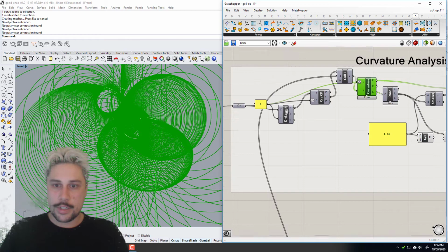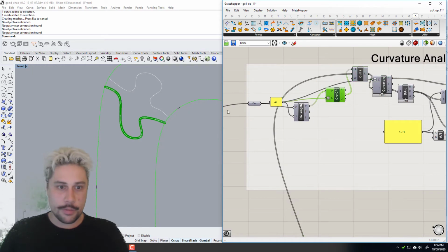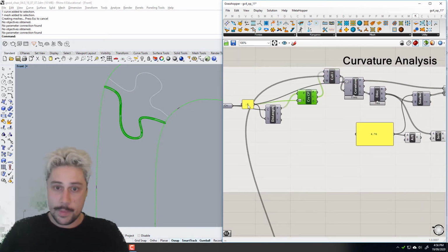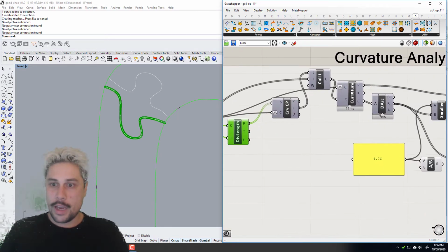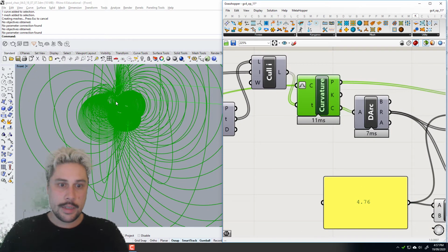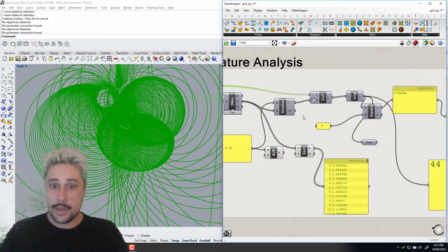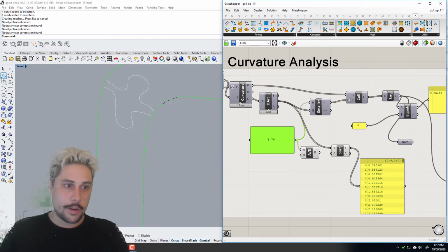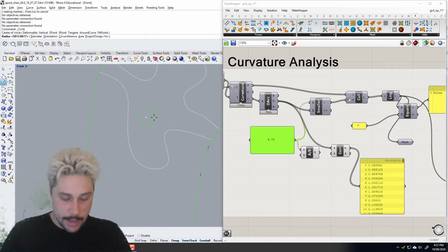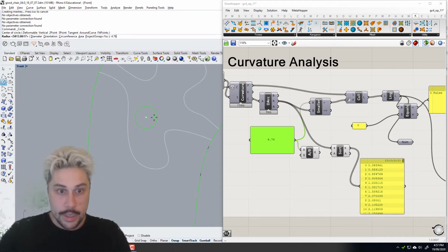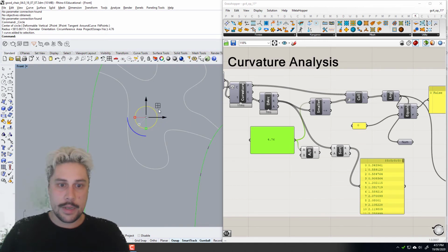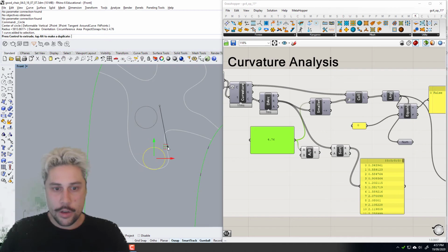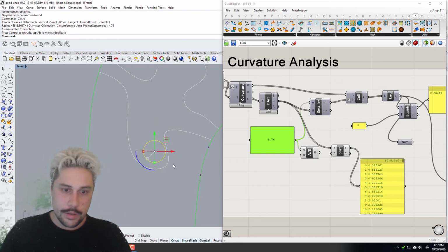So I pretty much take the curve, divide it into a bunch of points that are 0.2 long, and take a curvature analysis at all those points. Because it's going to be made on a CNC machine, using a drill bit that's about 4.76 millimeters, I need this drill bit to be able to mill out the curvature without encountering a position where it's too tight to get into.